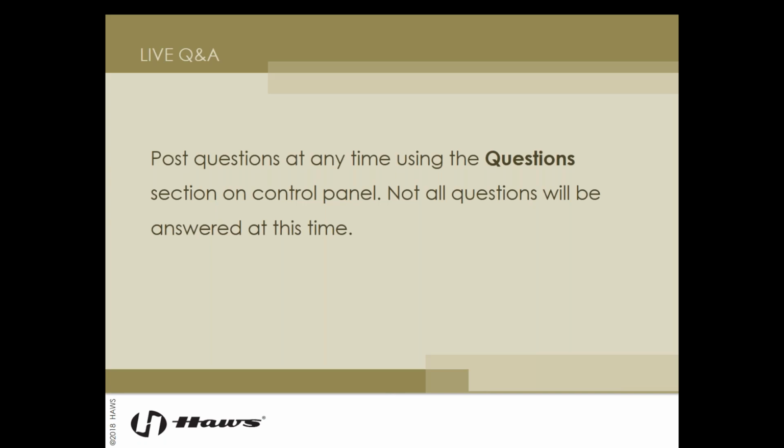Great. Guy wants to know, do drinking fountains installed outside, such as ball diamonds or play areas, have to comply with the high-low standards? Yes, they do. There's specific information in the ADA. Let me see if I can find you a quote.